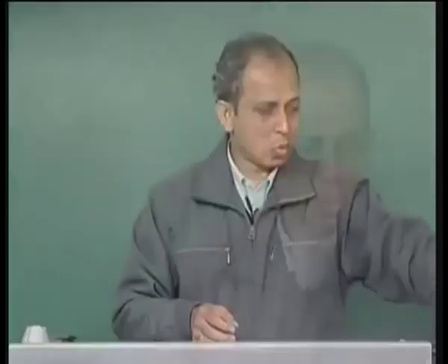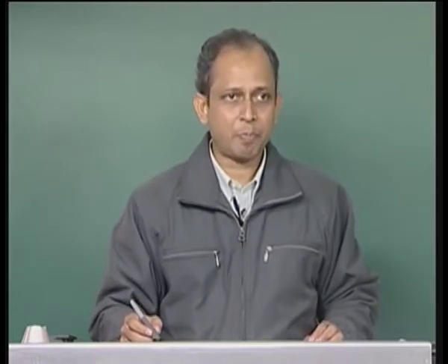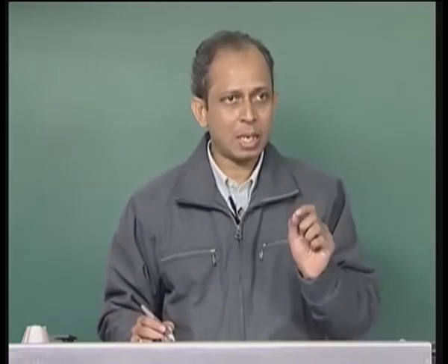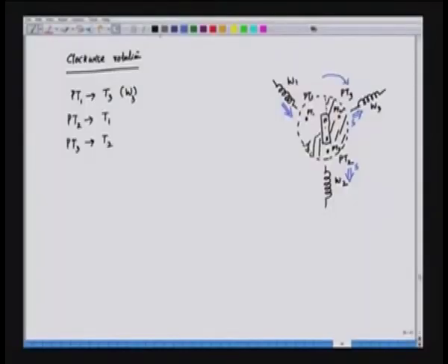Now if we come back to our discussion here, as the rotor rotates, the stator field goes on shifting. So as a result, we have a drawback, and the drawback is the torque pulsation. Now if we see the expression for the torque, torque is equal to K psi 1 into psi 2 into sine of the angle between them. So we can say sine of gamma. So psi 1 could be the stator flux, psi 2 could be the rotor flux, and gamma is the angle between psi 1 and psi 2.